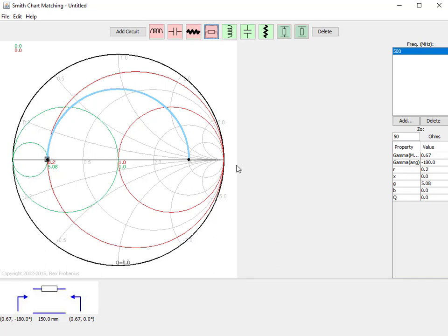And so the square root of the product turns out to be, let me get this transmission line clicked here. If we set this to 22.3, I believe, that's going to shift that termination to a matched termination. So that's a quarter wavelength matching section.